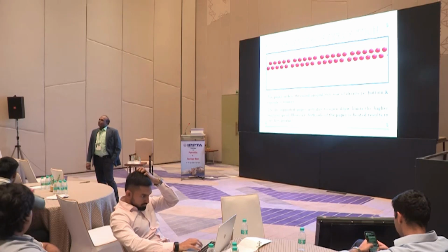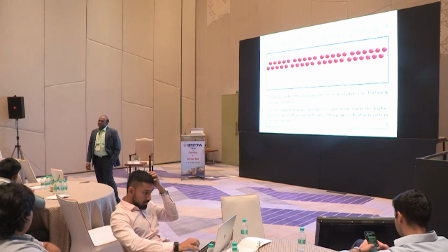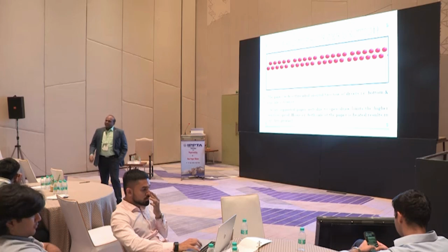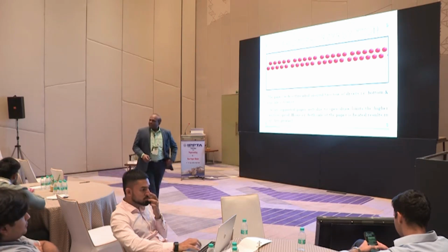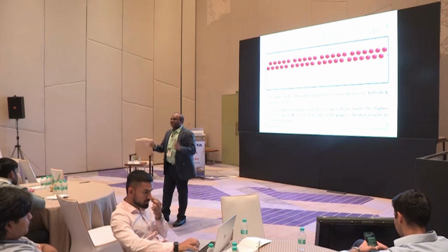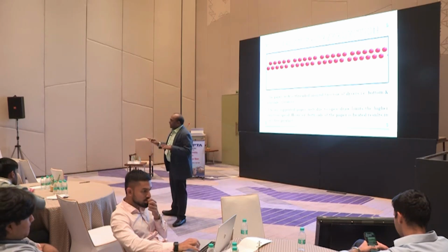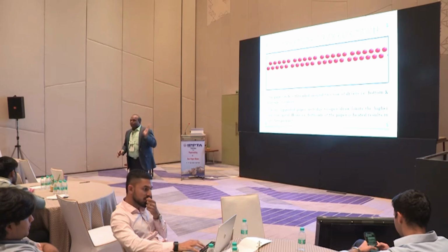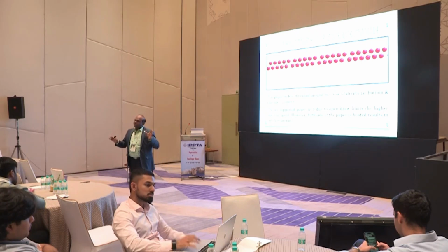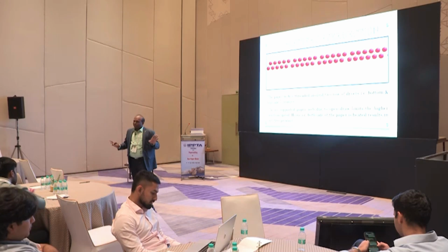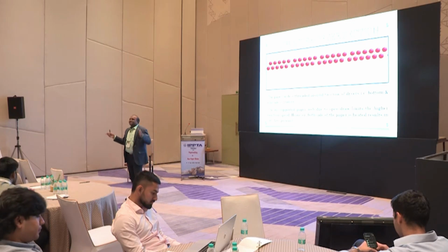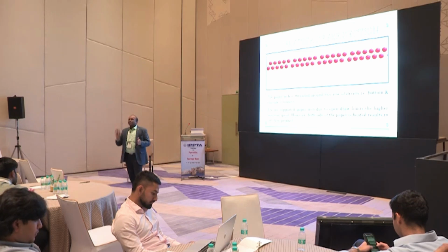Actually, the shrinkage will be around 10%, because as you take a new cotton shirt and give it for stitching, after that you could not wear it because it will get shrunk. Similarly, the width of the paper machine will be more at the wire part, and the width of the machine till the end section will be the same, but the paper will get shrunk. For example, if you are considering 6 meters width of the pulp slurry flowing onto the wire, the final product will be coming around 5.5 meters only.